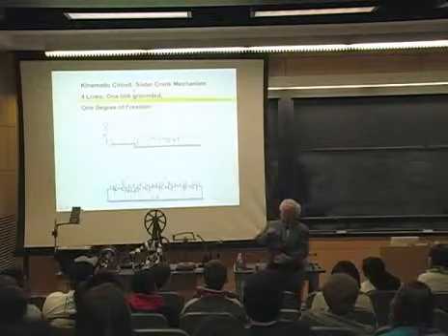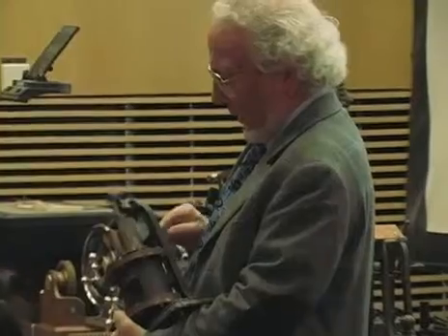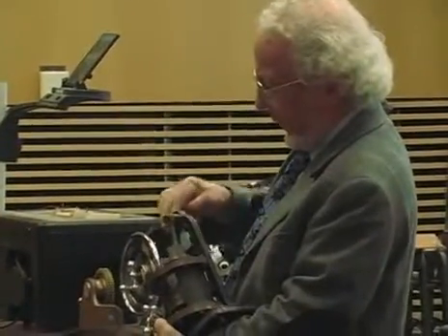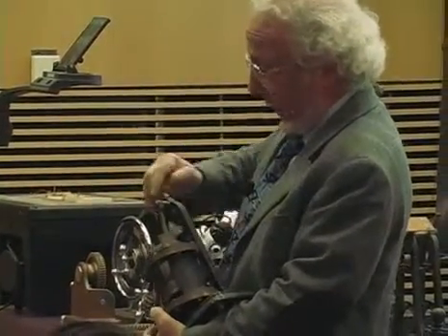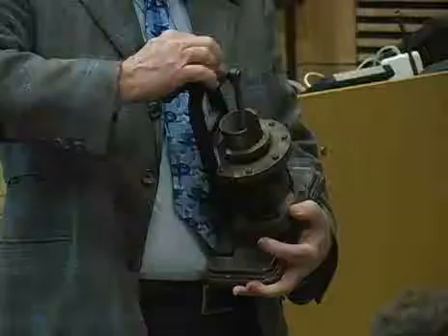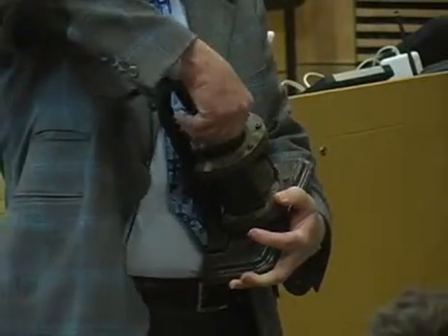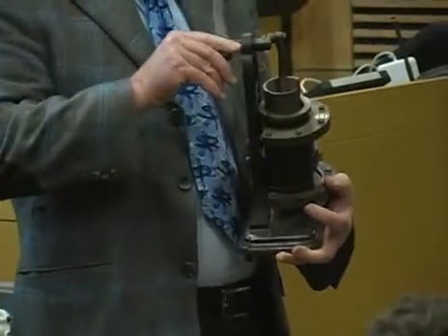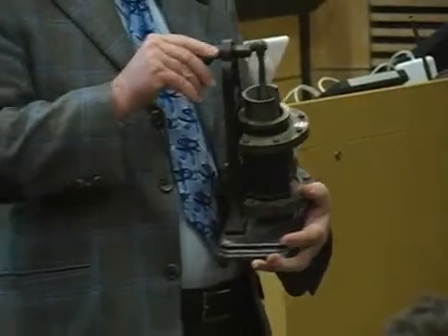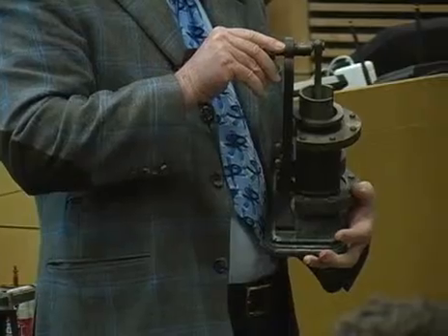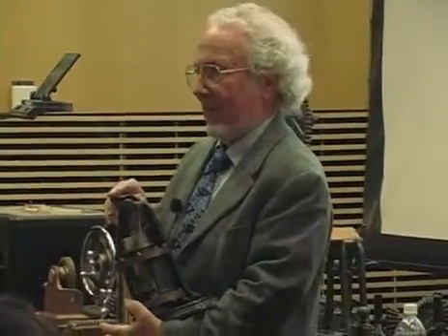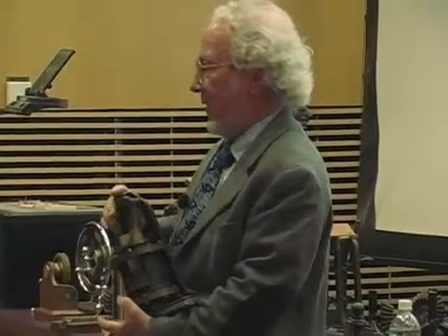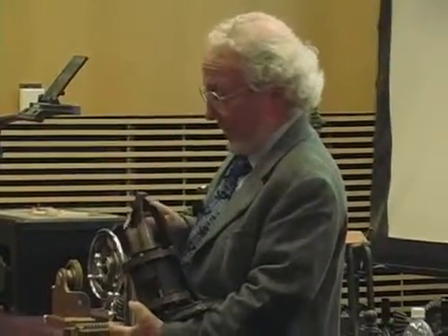You see there's a crank, there's a connecting rod, and I can identify 3 elements here. I have the crank, I have the connecting rod, and here is the slider. But where's the 4th link? Where's the 4th link? Is it the handle? The handle is the crank.